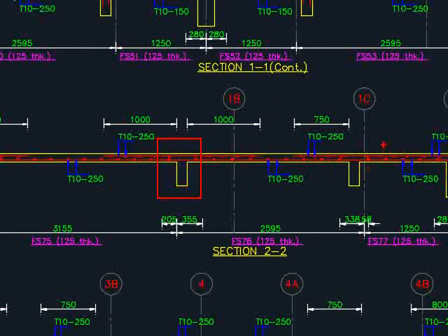You see at the support here, normally you need to provide the top reinforcement, and normally there is a certain length that you can cut your reinforcement, and when the two supports are too closely spaced, the region of unreinforced area may be quite limited. If this is too close to each other, it makes no difference if you have the reinforcement bar to be continuous. Of course, this will lead to some wastage of the material, but it significantly improves the productivity of the work.